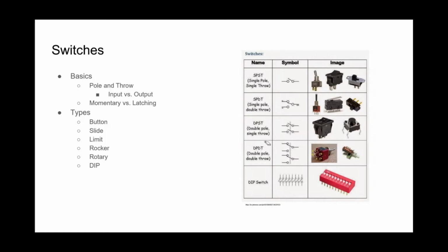All right, now let's talk about momentary versus latching. Momentary is pretty straightforward. Basically, it means that you have a switch that doesn't like to stay connected. So if you push it once and you let go, it's going to come right back and disconnect itself. You will typically see those with things like these breadboard switches right there, or this limit switch right there. Those are both momentary switches, which means as soon as the pressure is released, the connection breaks.